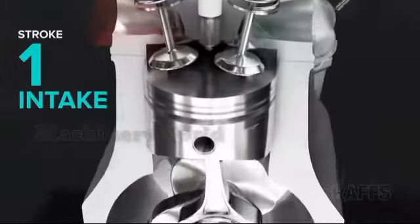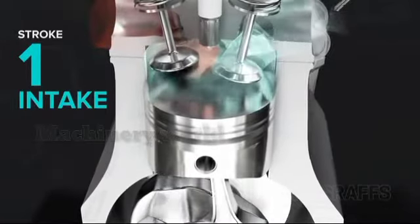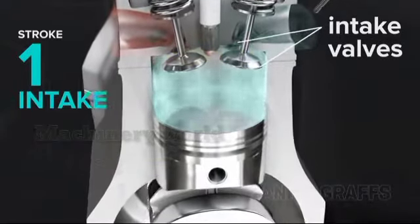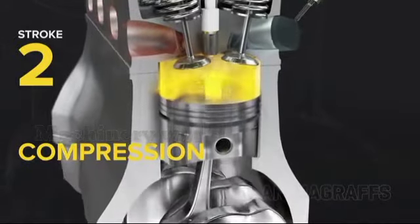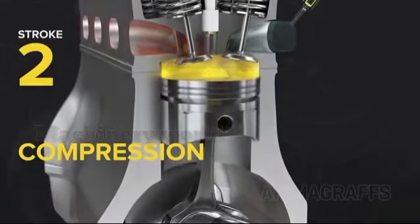First, intake. The piston descends, sucking an air-fuel mixture into the cylinder through the intake port, with both intake valves open. Next, compression. With all valves closed, the piston comes back up, compressing the fuel and air mixture for more powerful combustion.